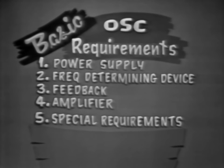There may be other requirements depending on the application of the oscillator, which you'll discover when you study a particular piece of equipment. But the main idea is that all oscillators are basically the same. So whatever the type or the name of the circuit, all oscillators will require a power supply, a frequency-determining device, feedback, usually from an amplifier. Now, if you apply these basic principles, oscillators will be much easier to understand.